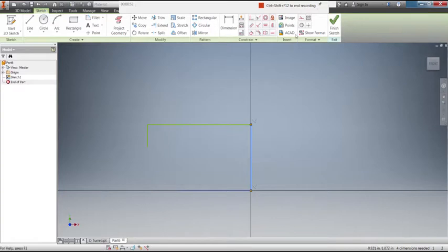So I'm going to make it a center line. I'm going to click on it, and then up top, I'm going to choose center line. And that's going to change it to a center line. Now I can add dimensions and refer to the center line, and it will understand that that's a center line and make the dimensions diameters. So I want to go from here to here.